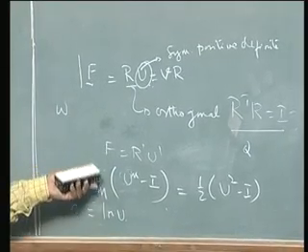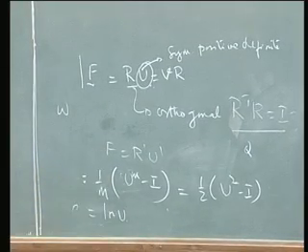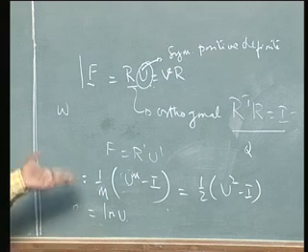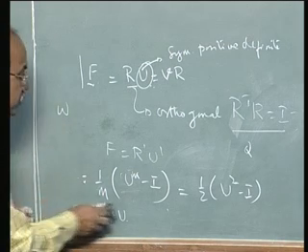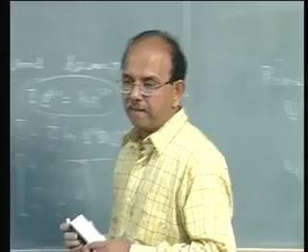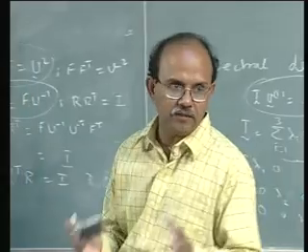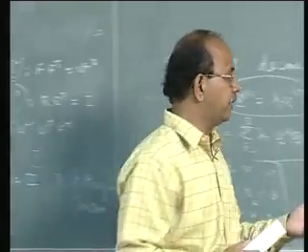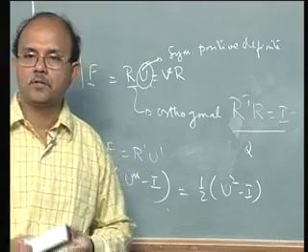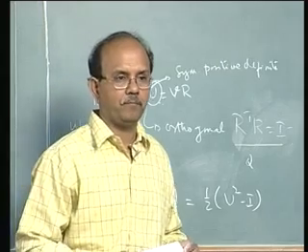These are other generalized strain measures. We may not use all of them in this course, and when it is necessary, I'll define it. But I just want to state that there is nothing very holy about the definition of capital E. You can define various strain measures by using various powers of U as well.